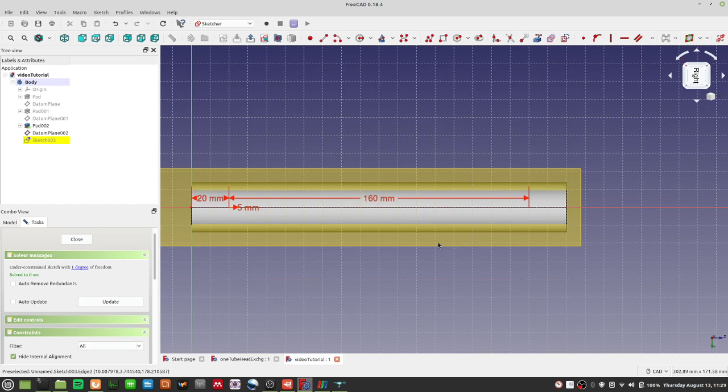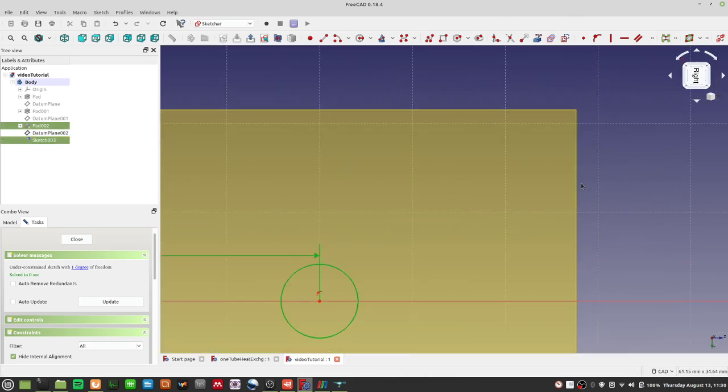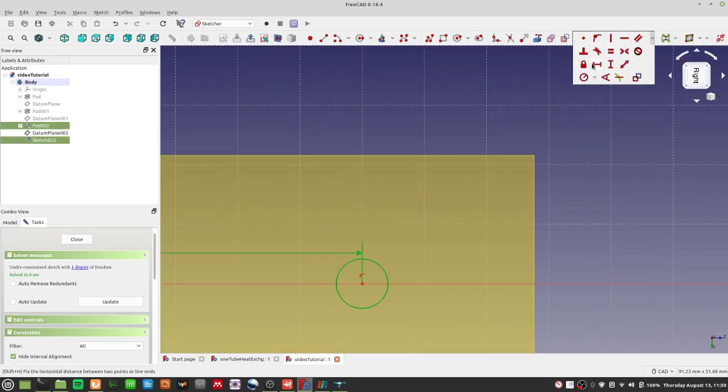And if this whole heat exchanger is 200 millimeters, having the other side 20 millimeters from the end means that this is 20 millimeter, this is 160, so both of them add together, you have 180 millimeter, so that the other hole will be bored 20 millimeters from the end. So once I do that, I can close this and let's make this radius 5 millimeter.